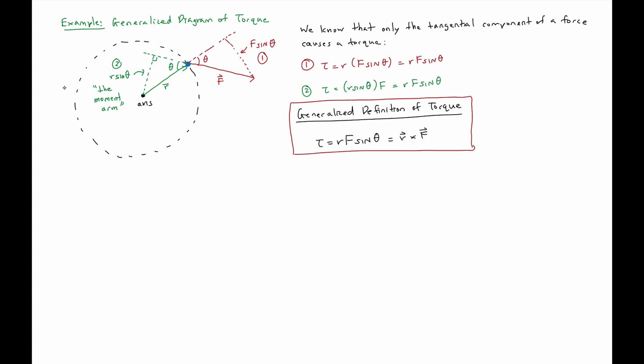Now, when we talked about forces back in the linear world, we also talked about work and power. So we do have to talk a little bit about work and power. Similarly, we can look at rotational work and power. And to calculate work, it's very similar. Remember, work was equal to force times displacement, so F times delta x, but using one of our conversion equations, we can represent delta x in the rotational world by multiplying it by r delta theta.